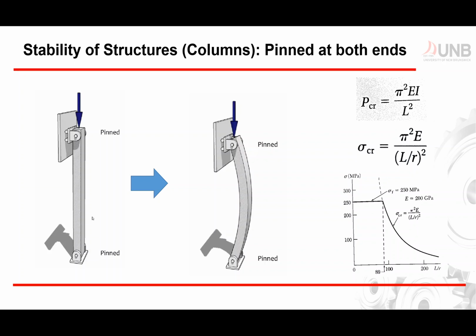Now, note that buckling takes place before yielding, which means that if you design a structure, it's possible that your buckling may happen after your yielding. If that's the case, your yielding will happen first and your buckling will never happen at all, which is the case here. So you see this curve from high slenderness ratio, and then once you lower your L over R, the critical stress increases, which is good, until it reaches a yield point, which is 250, and then this would be your failure mode, which is based on yielding and not based on buckling. Now, the idea in building your columns is you want your structure to fail more on yield rather than buckling, because buckling happens at a lower amount of stress.